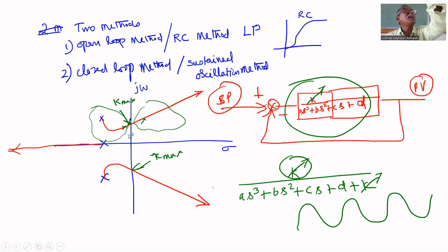Suppose this beam here, actually this much size beam is not at all required. For one day use, suppose this building is used only for one day, this much is not required. 1/6 of this is sufficient for this much load. But they are putting 6 times higher. Why? Factor of safety. So the building is designed 6 times safer than required, because if any earthquake comes, it should withstand.